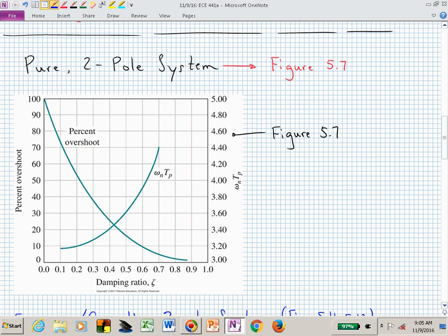And that influences your angle. Or if I want a 5% overshoot, now I need a 0.7 value for zeta, and we said that's a nice selection or option if you get complete freedom over the speed of response and the overshoot and the behavior. 5% overshoot's a pretty nice value, or an angle of your two dominant poles of 45 degrees.